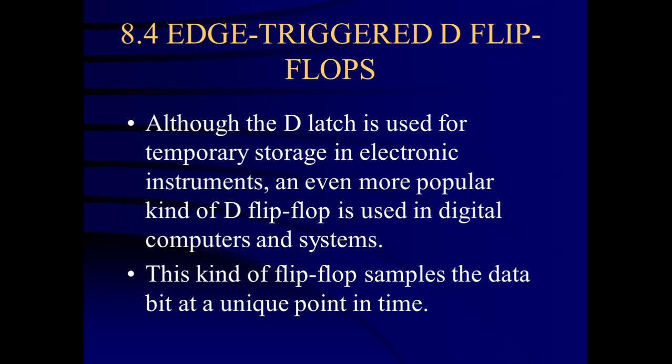Edge-triggered D flip-flop. Although the D latch is used for temporary storage in electronic instruments, an even more popular kind of D flip-flop is used in digital computers and systems. This kind of flip-flop samples the data bit at a unique point in time. That means at a unique point of time when the positive edge of the clock pulse occurs, only at that time whatever data is presented is transferred to the output. That's why this kind of flip-flop samples the data at a unique point in time in a D flip-flop.